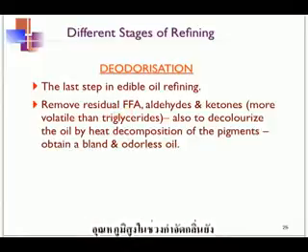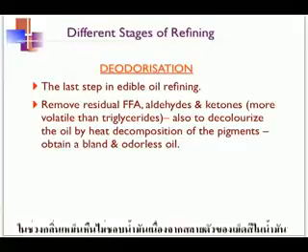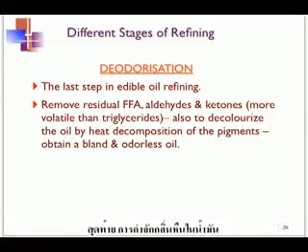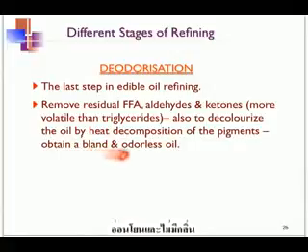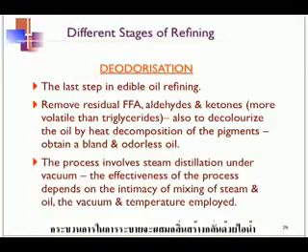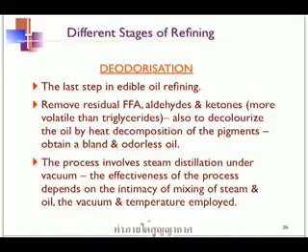The high temperature during the deodorization also would decolorize the oil because it will decompose the pigments in the oil. So the final deodorized oil actually will be bland and odorless. The process of deodorization is basically a steam distillation done under vacuum.